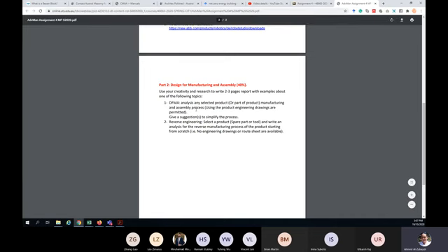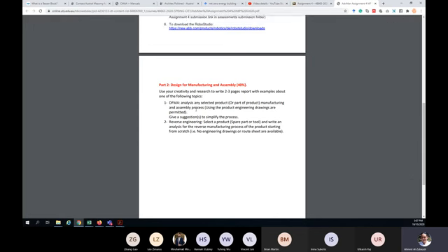And I gave you some suggestions for the first operation. We have, for example, the laptop, which usually has about 16 screws to be built in. Try to replace those by using some fixture which can hold the laptop rigid and reduce the number of screws. This, of course, is going to reduce the assembly process time, and thus we're going to save some money.